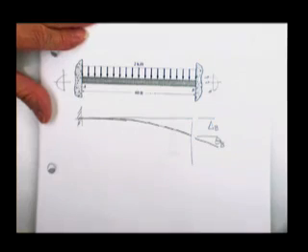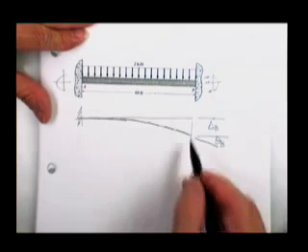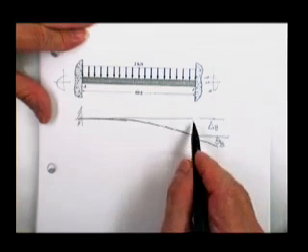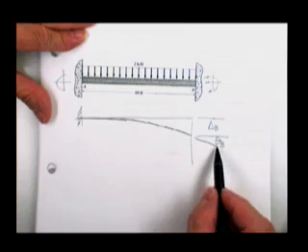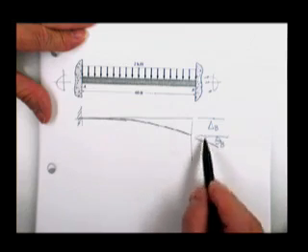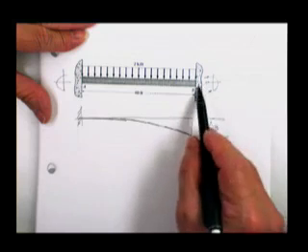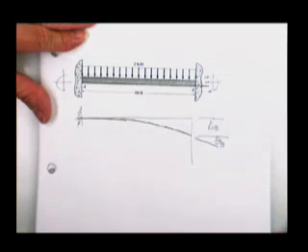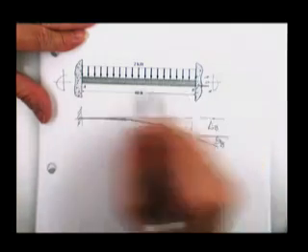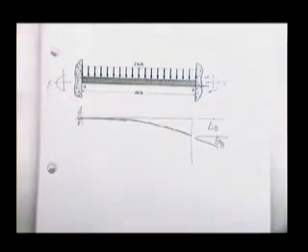And therefore, you will not only have to go to the construction shack and pick up a hydraulic jack to push this point back up, you will also have to put a thing on there with a moment maker and put a moment on it so that when you get it back up to here, it'll come back into the wall with no slope. And then the third thing, there are no horizontal forces on them, so really don't have to worry about those 2.